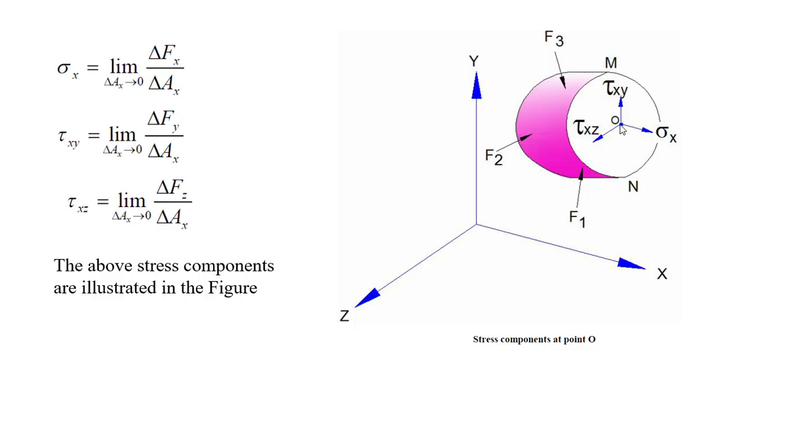And if you see in this direction, shear stress will be parallel to the area of the cross section. Here also we can see the area of the cross section; the force in y direction will be parallel to the area of the x. In x direction, the y directional force will be parallel to the x surface. The x force applied in x direction will be parallel to the y direction. These two are the shear components which are parallel to the cross sectional area, and this one is the normal component which is perpendicular to the cross sectional area.